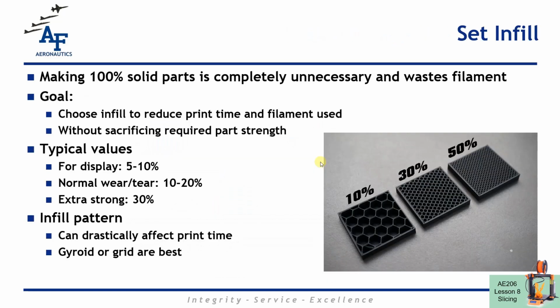Okay, we also need to change the settings for the interior of the part. We do not need to make a part that's 100% plastic on the inside. It's a complete waste of filament. Okay, the amount of filament that we put on the inside of the part depends on what we're using the part for. If it's just going to be something that's sitting on your shelf and it's really just a display part, 10% is fine, or even 5% is fine sometimes.